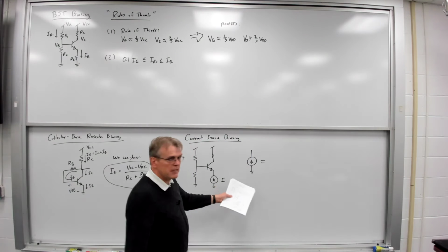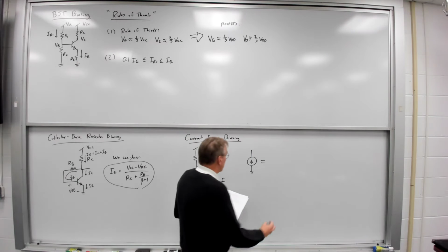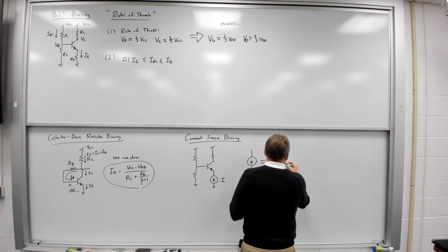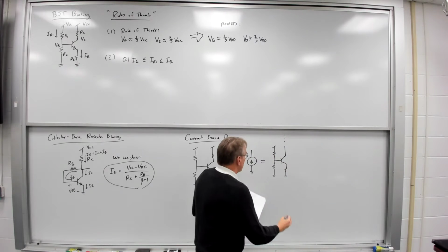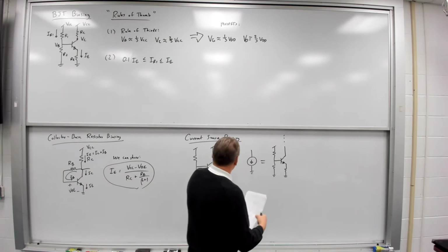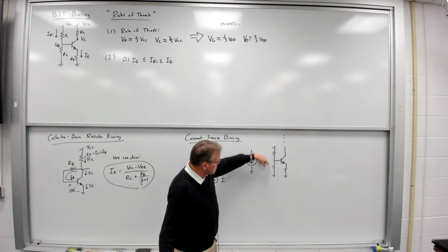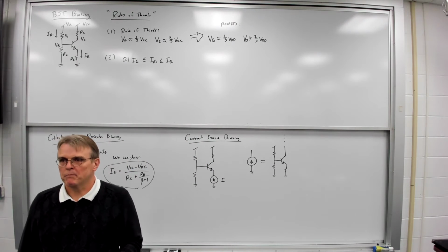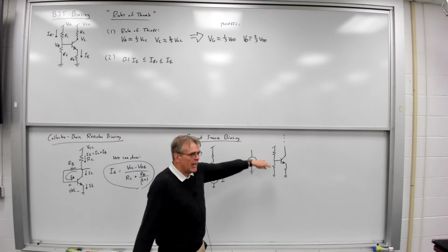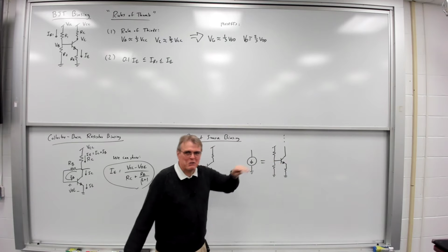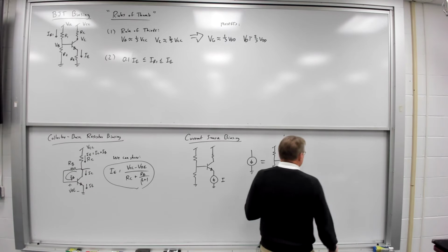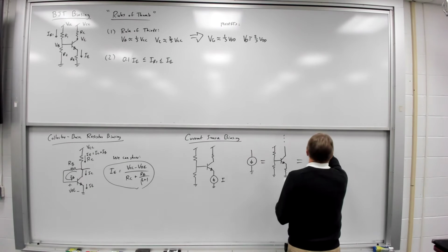Well, you can replace that ideal current source, of course, with another transistor. And so I can simply take this and then put in a second transistor with its own bias network, its own emitter resistor, and I can go and set the current with that. But of course, all you're doing is you're pushing the accuracy issues over to that circuit too. So another way to do this is using the current mirror, just as we saw with the MOSFETs.